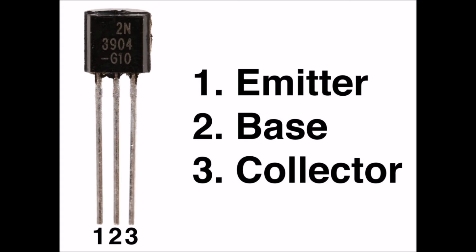Capacitors C2 and C3 block DC to or from the external input and output circuits while letting the AC signal pass. Resistor R4 keeps the output signal from shorting out through the power supply. A signal enters the common emitter circuit through C2, so the signal causes the base current, IB, to vary.